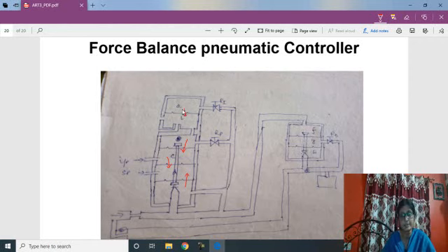As a result, the pressure of this chamber will rise, causing the pilot valve to move towards the nozzle direction, so the nozzle feedback pressure will rise. If you can remember the diaphragms, then you can analyze the action.